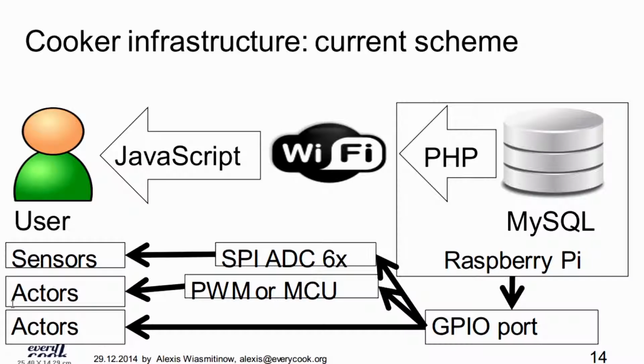We tried many things, but below 24 bits ADC resolution, a scale is quite tricky to make. But there are chips available and we can read them over SPI. So we have the load cells, the pressure sensor and the temperature sensor going over that ADC. The interface is now just a web interface in JavaScript. Later, we of course want to make an API so we can have native apps for better responsiveness of the interface.